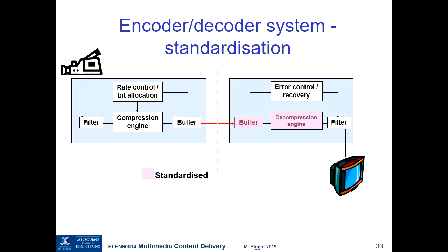High, or actually a range, but noise will have, in theory, white noise has all frequency components, but noise will introduce some randomness in the pixel values, and so to accurately represent those changes, we would have to have a lot more high frequency components present. And if we waste our bits defining the high frequencies that would allow us to reconstruct a signal that's just noise, that's a bit of a waste of bits. So if we filter them out initially, if we can do so without smearing the whole picture, then we save bits and the whole process is more efficient.